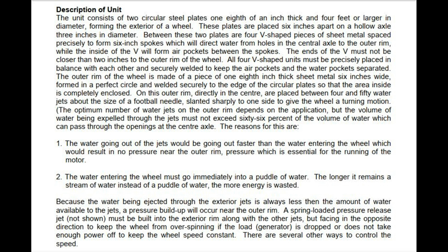2. The water entering the wheel must go immediately into a puddle of water. The longer it remains a stream of water instead of a puddle of water, the more energy is wasted. Because the water being ejected through the exterior jets is always less than the amount of water available to the jets, a pressure build-up will occur near the outer rim.